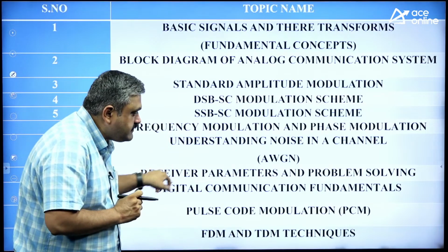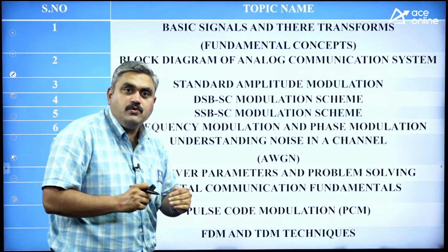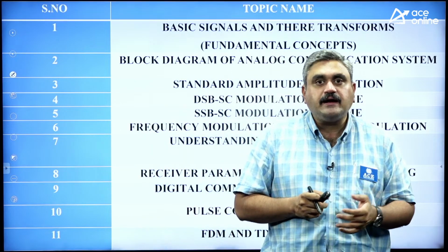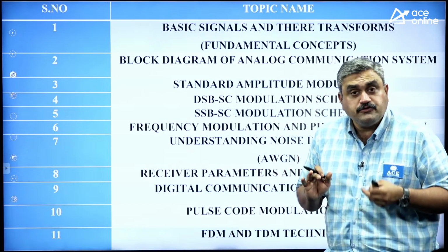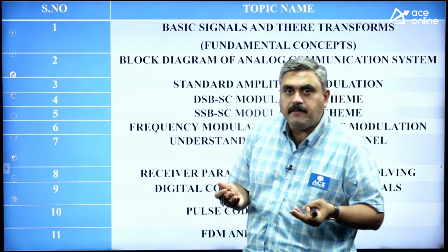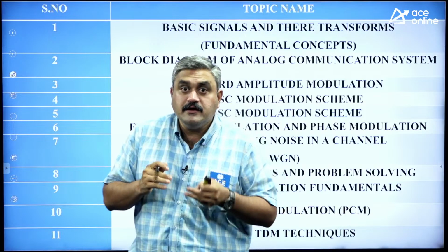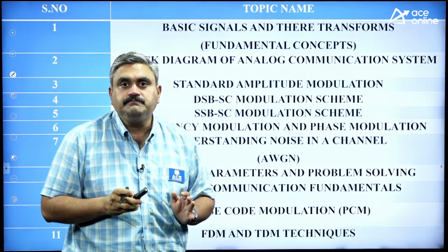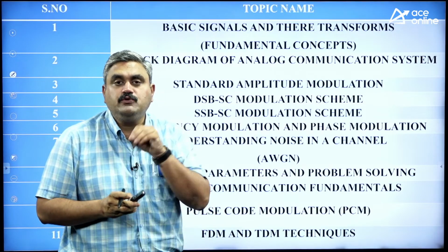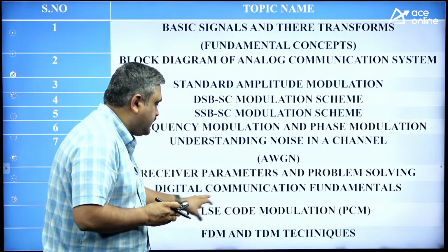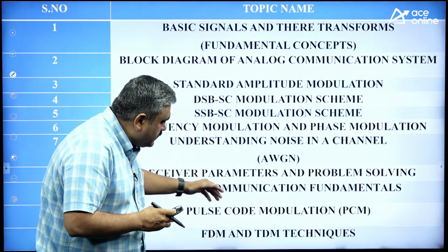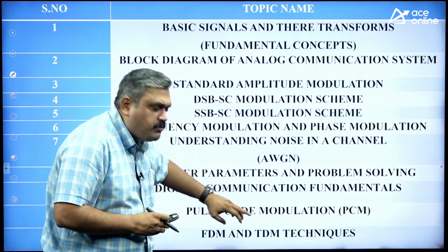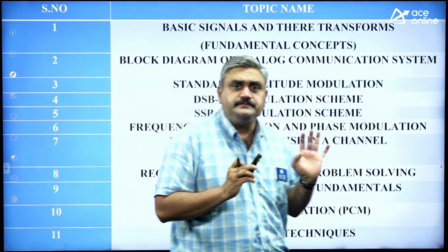But from here it is about digital communication. How you transmit your data using binary format comes under digital communication. What blocks do you have? You will have a sampler, a quantizer and an encoder. Those are also clearly mentioned in your syllabus. What are those blocks doing, and what are the formulas related to those blocks? We will discuss that in this area. The modulation scheme related to that is pulse code modulation, and this topic of pulse code modulation is completely formula oriented.